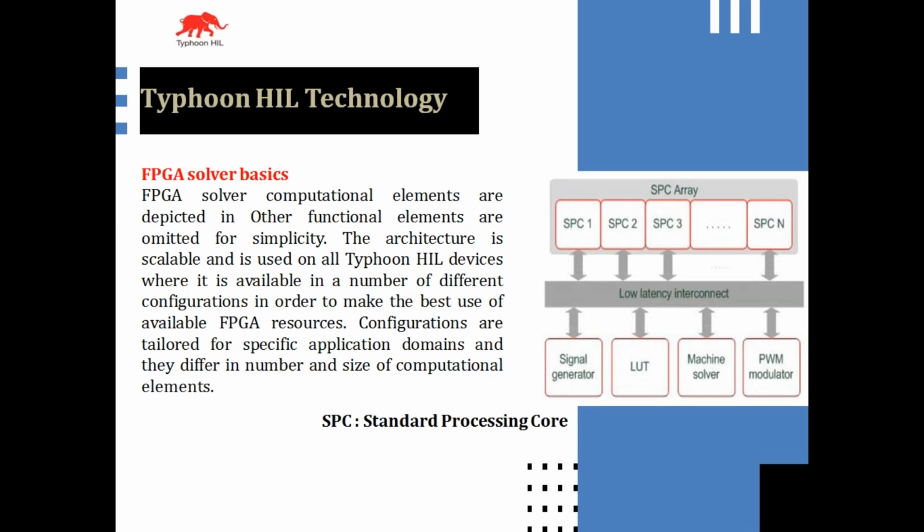But remember, latency is a factor which depends upon the hardware characteristics, software settings and the model itself. But we have a very unique feature: with 20 nanosecond PWM sampling time and 500 nanosecond simulation time step, we provide ultra low latency and have set the industry standard for ultra high fidelity real-time emulation.